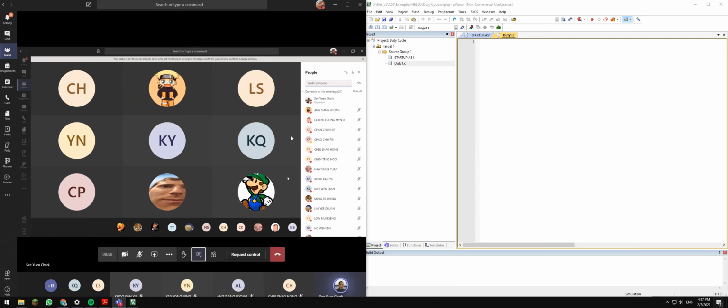So that's the reason I'm not porting it to ESP32 using Arduino. Because, to be frank, it's very straightforward because everything is already written for you. Whereas when you're using the PIC18 C compiler or PIC24 C compiler, you are actually designing that particular library. Whereas if you use Arduino, you just call the function. So in the end, time to market when you're using Arduino is faster compared to using XC16 or XC8, okay, and etc.